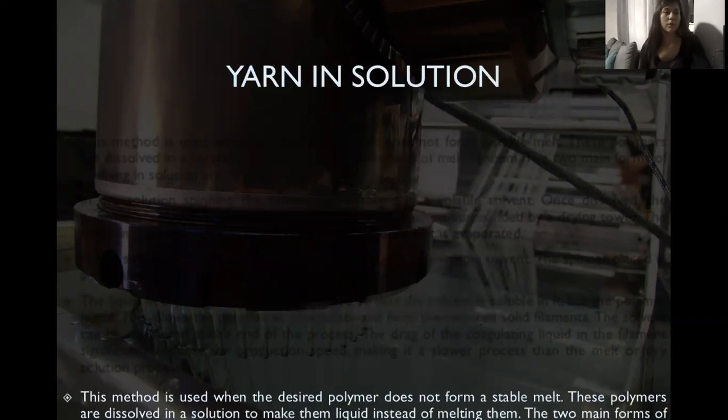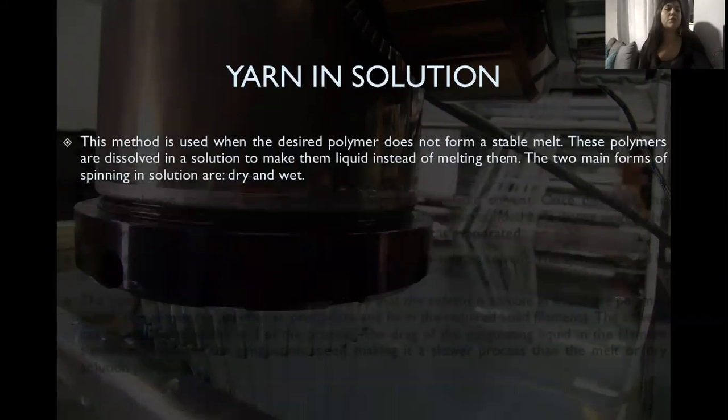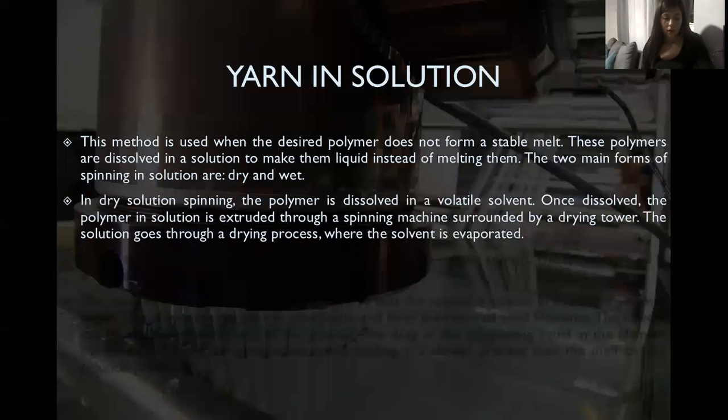Then comes the solution spinning process. This method is used when the desired polymer does not form a stable melt. These polymers are dissolved in a solution to make them liquid, instead of melting them. The two main forms of spinning in solution are dry and wet. In dry solution spinning, the polymer is dissolved in a volatile solvent.